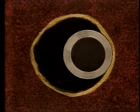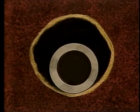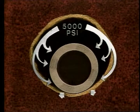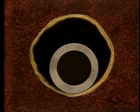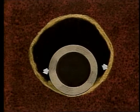Now, you're pretty much okay as long as the pipe is turning. It'll wobble and flop from side to side inside the hole, but as soon as you stop for a connection, it's going to settle down into that filter cake. The drill collars are going to be what gives you a problem because they'll lay flat against that wall, top to bottom. The tool joints on a drill pipe will tend to hold the body of the pipe away. So now we've got 5,000 psi pushing against all of the collars except this area where it's in contact with the filter cake. Here we've only got 4,500 psi. Now we're stuck. And the longer we stay stuck, the more the filter cake will build up in this area.